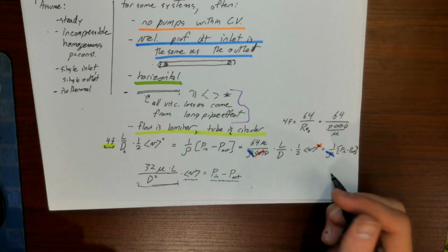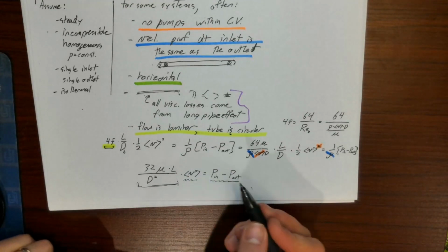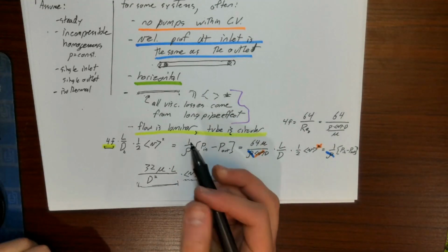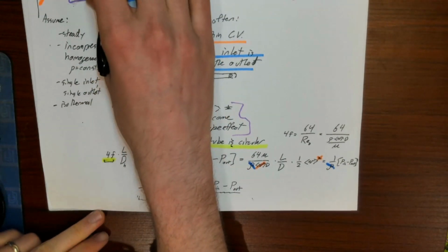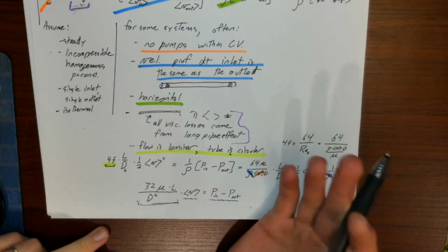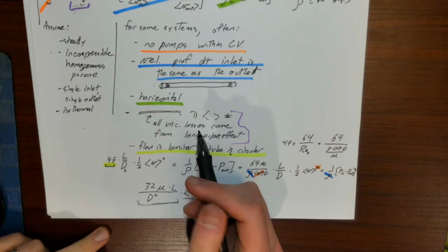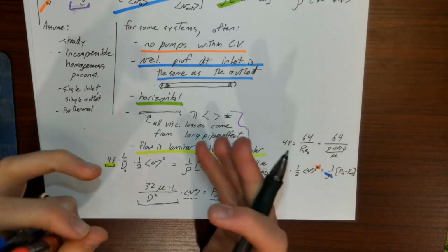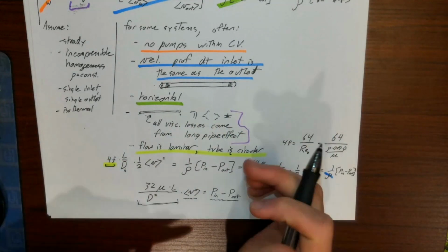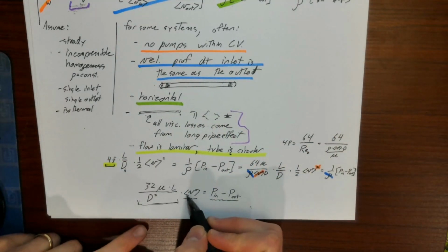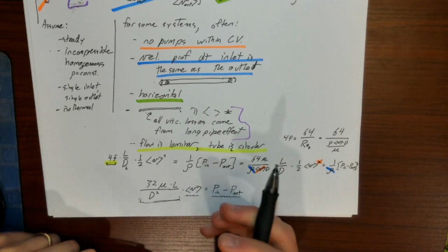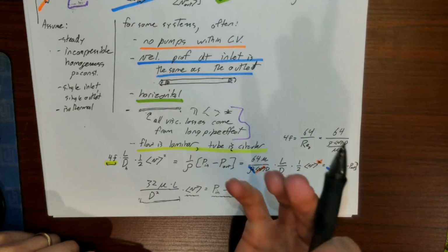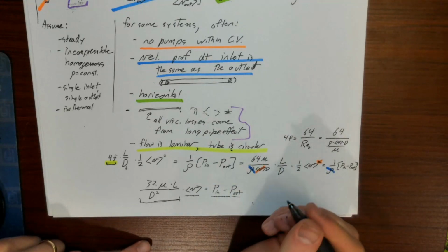One last thing that we like to do is, average velocities are sometimes useful, but a lot of times, particularly for microfluidics, or considering parts pumping blood around the body, or bioreactors where we're pumping flow to various parts of the system, it's not actually the average velocity that we care about for our engineering use. It's basically how much fluid am I pumping per unit time, in which case we care about volumetric flow rates.